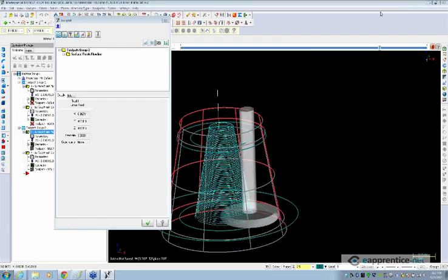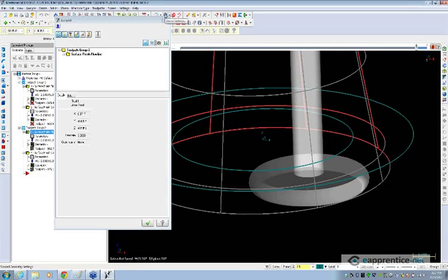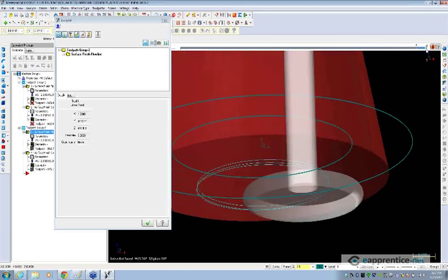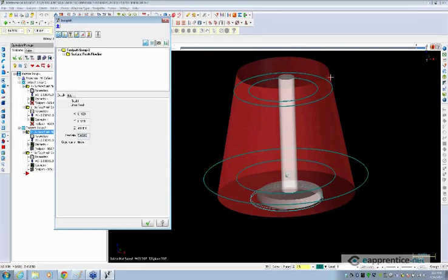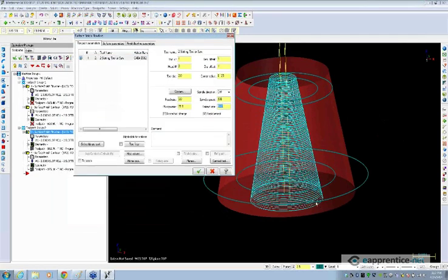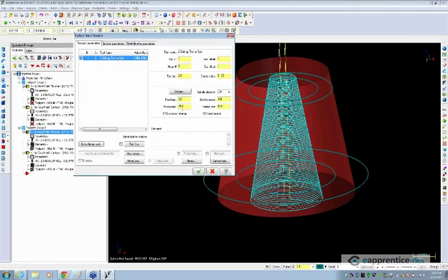We get down near the end here, and we'll restrict drawing. And as we finish the cut, we're still at 3, still at 3. So we're coming over here at 3 inches a minute. And now we're in the retract. So it uses the plunge value for the initial entry direction, and then it uses the retract value here for the retract. So you actually get 2 different values. Your plunge is for the entry. So you notice plunge direction, retract direction, and on the toolpath parameters page you've got plunge rate and retract rate. So it's using those values there.